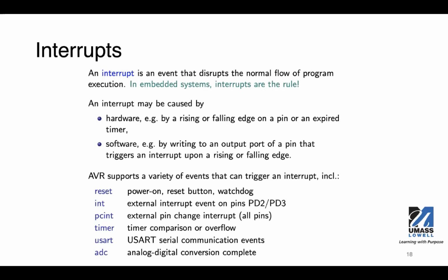The AVR processor supports a variety of events that can trigger an interrupt, including reset. If it's a power reset button or watchdog timer, that will trigger a reset interrupt. INT refers to external interrupt events on several pins, PD2 and PD3.